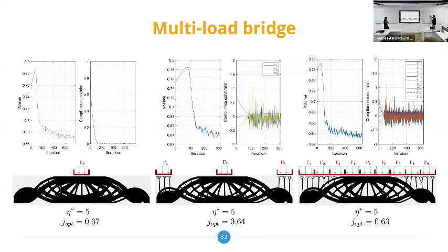And then maybe I can use a fixed epsilon. So the filter basically performs a convolution operation at each point, and then even if I'm refining at some point, if I use a fixed epsilon of 2 centimeters, for instance, then at some point I should start obtaining thinner and thinner solutions.